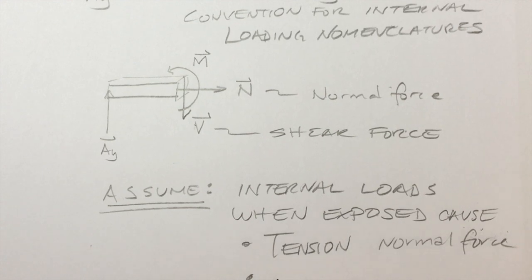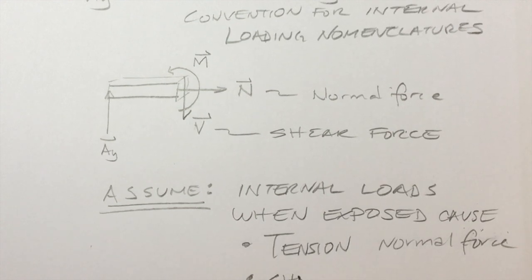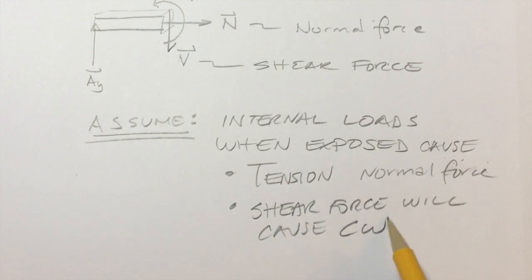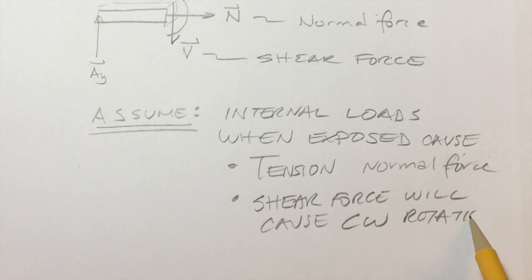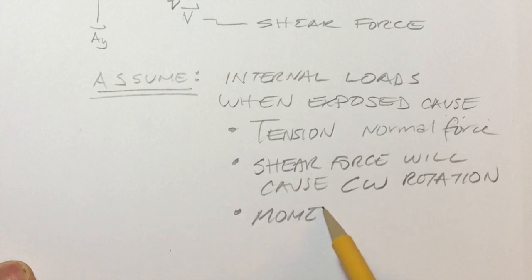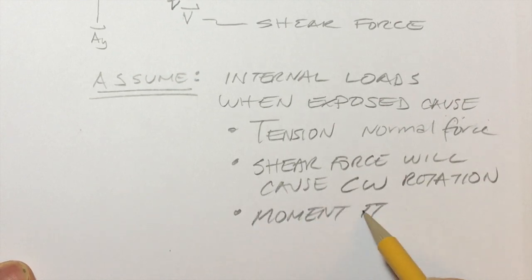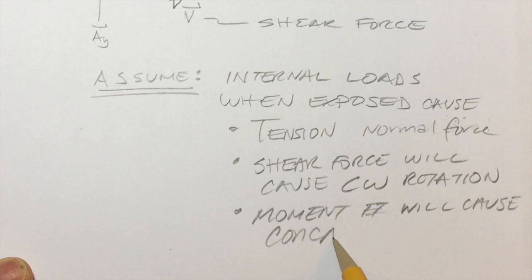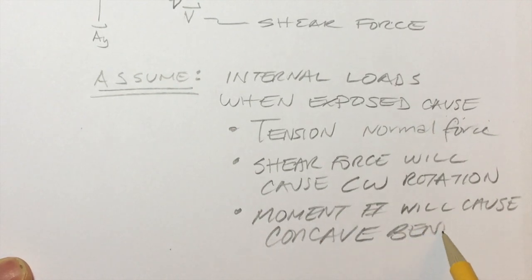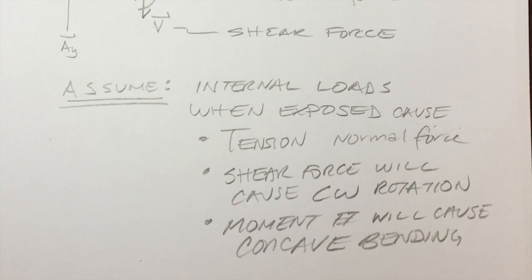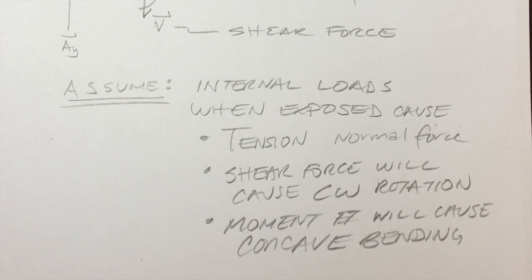You're going to assume that the shear force will cause clockwise rotation. And for the moment, moment will cause concave bending. So as long as we are all consistent with that, then the work that we do can be comparable, and it'll be easier to discuss it during the class.